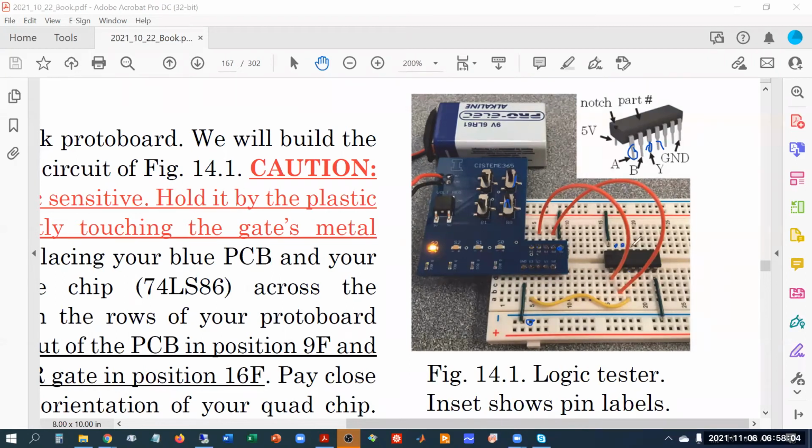If you ever get on your output a number that's in the ambiguous range, the ambiguous range is between 0.8 volts and 2 volts. The logic gate really hasn't decided whether that's supposed to be on or off. And so most likely there's something either wrong with the gate itself or one of the pins is not plugged in. Occasionally we've had some issues with a few of the AND gates, but they generally almost all work. So if you've checked your wires and everything and it looks correct, but you get some intermediate voltage or your circuit doesn't add quite correctly, try replacing the logic gate itself and plug in a new gate. I did that with one of the AND gates, and that was able to solve the problem because my wiring was correct, but my circuit wasn't working.